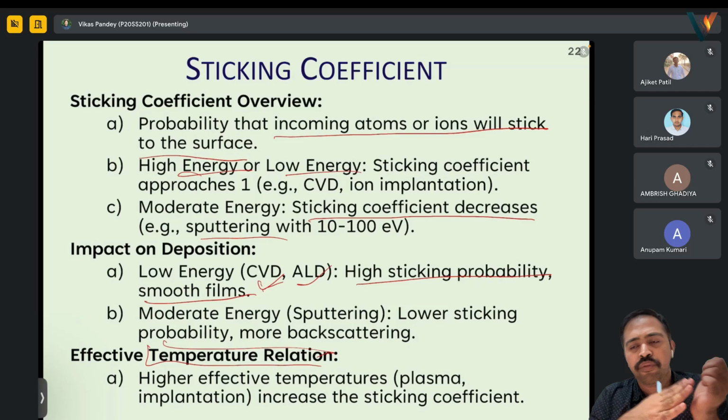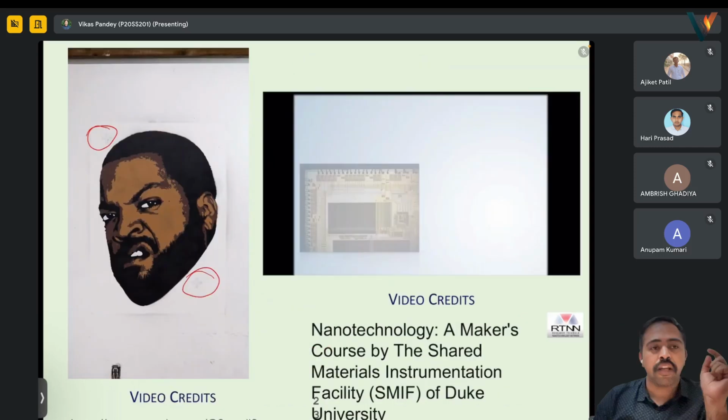Whereas in indirect pattern transfer, the pattern is transferred onto an intermediate layer and then stripped. That acts as a master layer, a master pattern, and that master pattern can be used multiple times. Example, optical lithography gives higher resolution, and it is highly repeatable. The same thing is fixed, that's why it has higher resolution and repeatability.